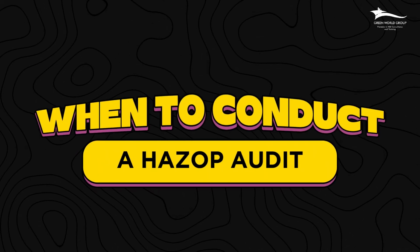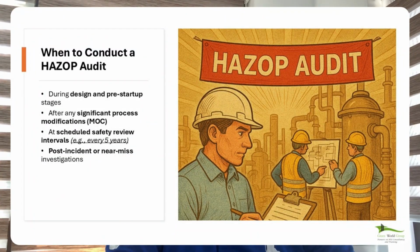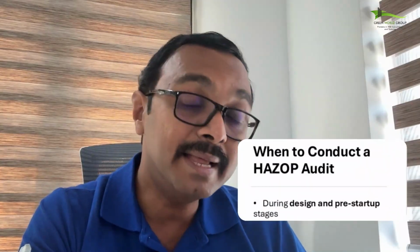Now the next part that we are going to see is when to conduct a HAZOP audit. As I said earlier, a HAZOP audit is not a one-time task. It's a regular as well as a situational requirement. So when should it be conducted? It is conducted during the design and pre-startup stages of a particular project or process, to ensure safety is built in from the beginning.